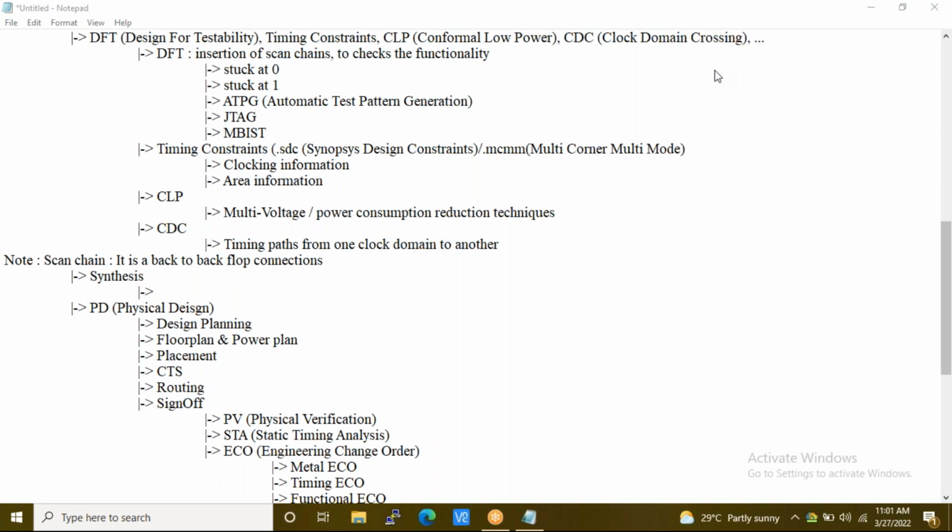Let us say at any point of time in your mobile phone, metastability happens. Even now, let's say I'm talking, and for some reason in my mobile phone metastability happens, my phone will stop working immediately. So we don't want that to happen. To avoid all these issues, we go with synchronizers between one domain and the other. Okay, I hope you understood this.